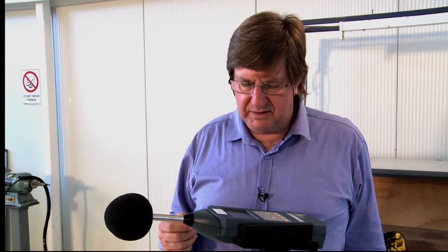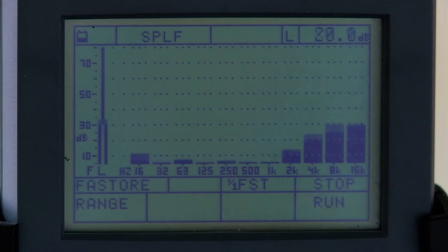People in home units, in normal residential places, aren't running around ringing bells, which is very high frequencies. The standard tests that we do for buildings is restricted to 125 up to 4,000. After 4,000, we assume that people aren't going to be introducing high frequencies.